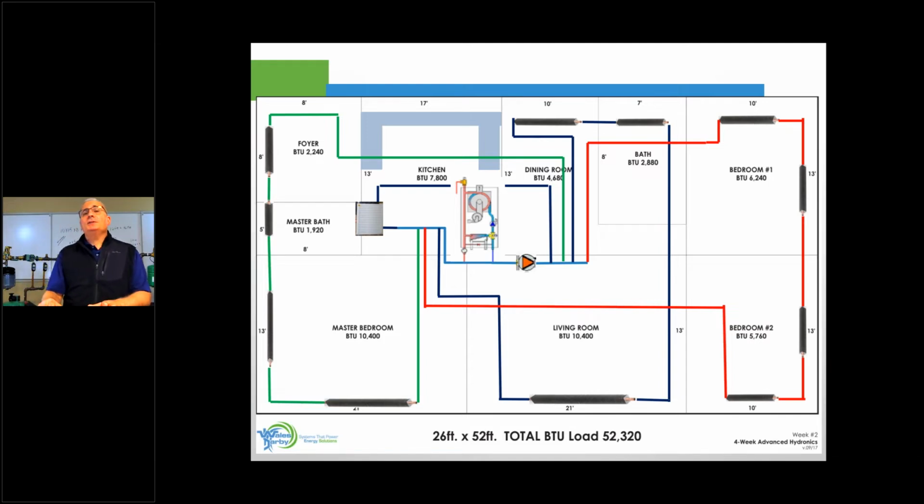All right, so we're going to zone this the way we are. Now, how do you guys want to zone this? Do you want to zone this with pumps or do you want to zone it with zone valves? That's another thing that we're going to talk about in detail when we go into our next classes. It's a small project over here. I would do this as one single circulator and zone valves. Zone valves are leading on that. Okay, fine. I know when we cross the river and go into the island there, they do like to lead with zoning with circulators. And that's an option here too. But again, if you figure out the BTUs that you need, the GPM you need per zone, they're going to be so small, zoning with circulators could be kind of rough, but we could do it.